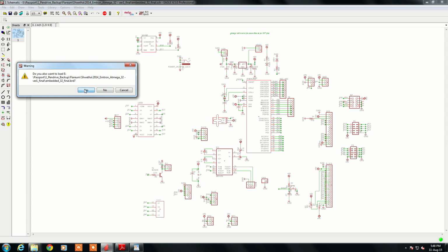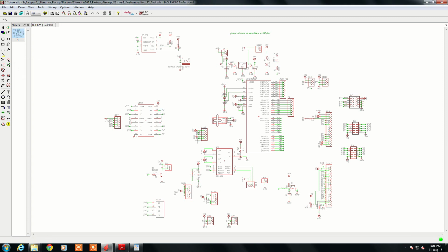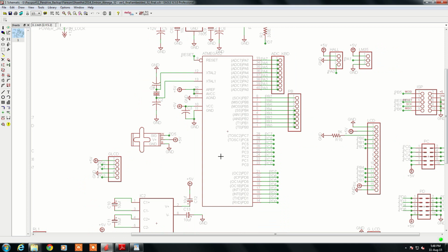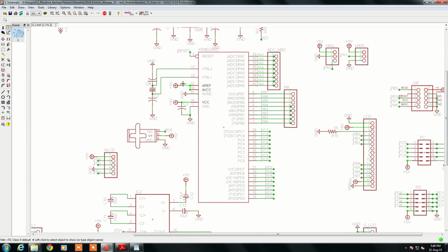This is the most popular circuit diagram which a number of students use in training programs. An ATmega32 based microcontroller, where as you can see there is a crystal with biasing capacitors, and VCC and ground are connected. If I highlight, say for example, my VCC line, you can see the same symbol is connected here, here, and on the connectors.